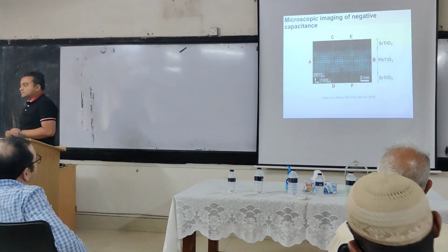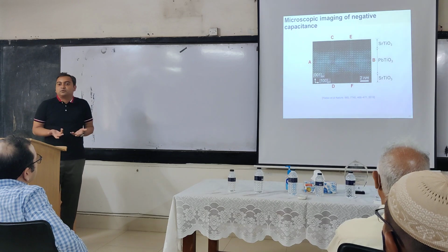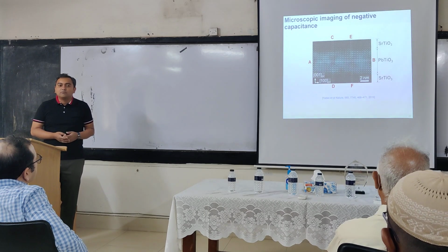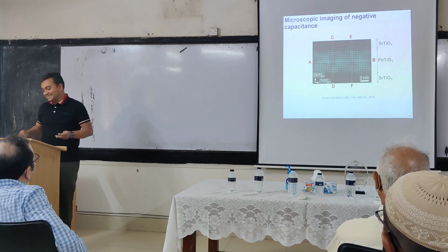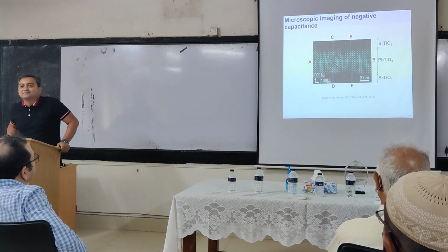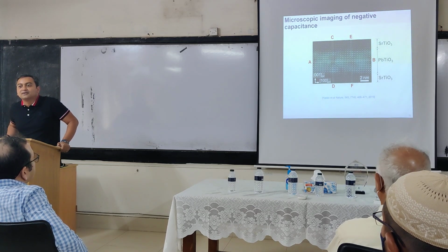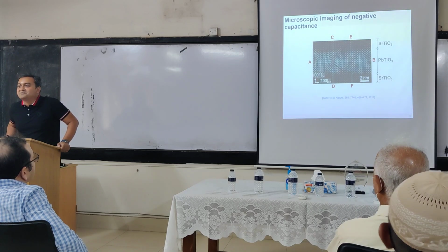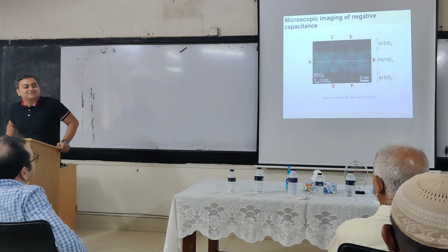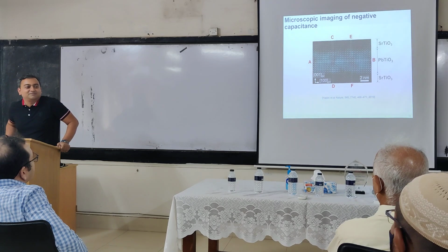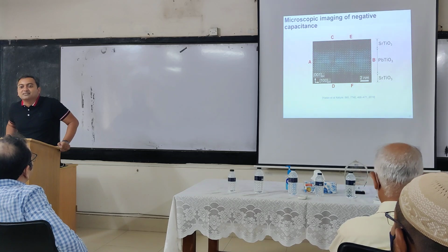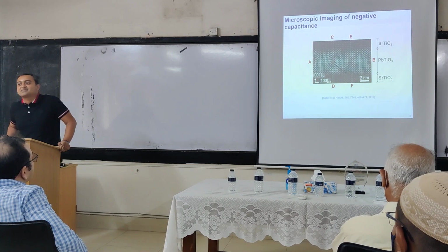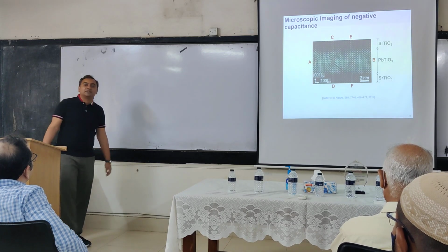Okay. Now, can I know the electric field inside? If there is a polarization, as we discussed, there is an electric field. How many of you have already looked at PN junctions? Everyone? Does a PN junction have a built-in field? Can we measure it? Yes? How? The barrier voltage. No, not measure, but we have to calculate it. How can we measure voltage? Can I put a voltmeter across a PN junction and measure it? No. You cannot measure the internal electric fields because it does not show up at the terminals.